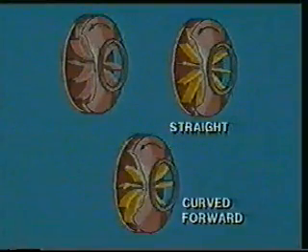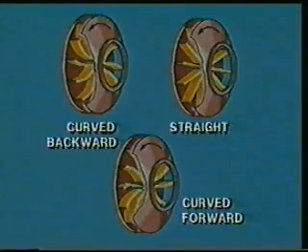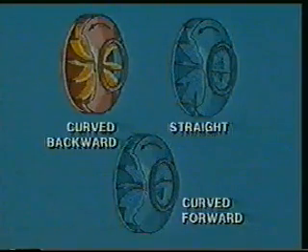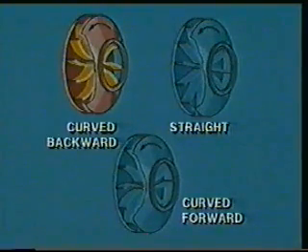The blades, or vanes, on an impeller can be straight, curved forward, or curved backward. Backward curved vanes are the most efficient and stable. However, since backward curved vanes cause the gas to leave the impeller with less velocity, there is less velocity to convert to pressure. Most oil-filled centrifugal compressors use the backward curved vane impeller.